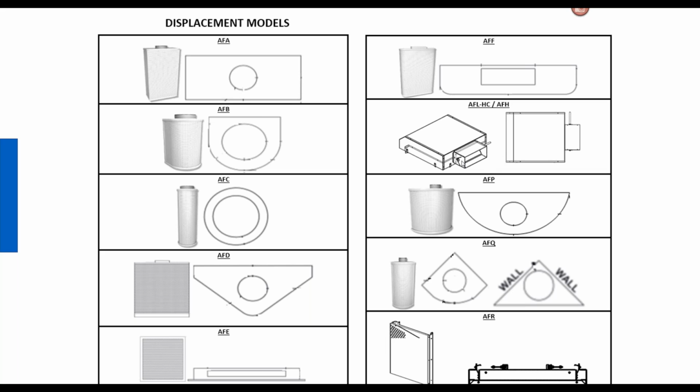In heating mode, a damper structure switches over to force the air through a linear slot, so your warm air is discharging at a high velocity, as it would in a traditional overhead. In cooling, it switches over to a perf face that slows it down because it has a low free area. This is the best of both worlds, and it should be launching within the next few weeks under the name AFH.